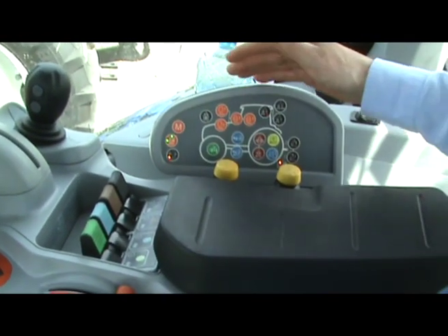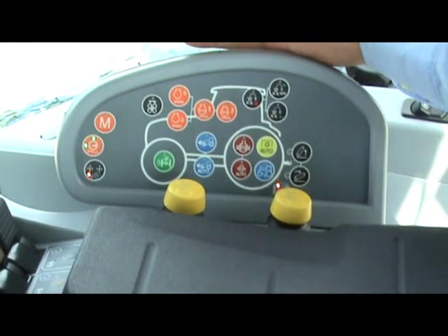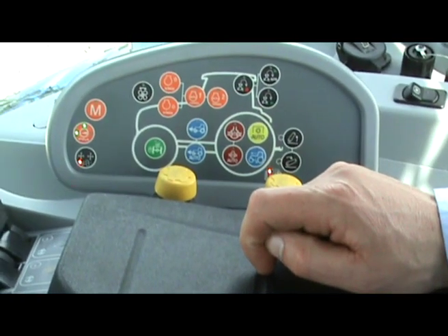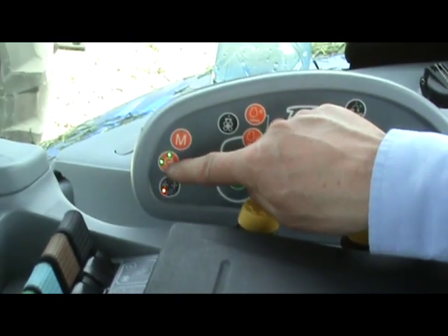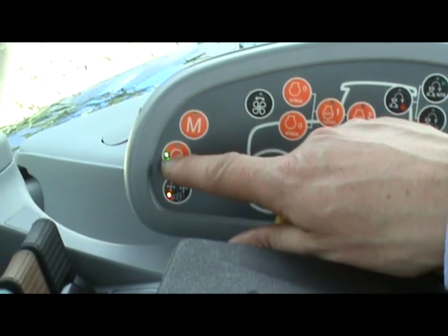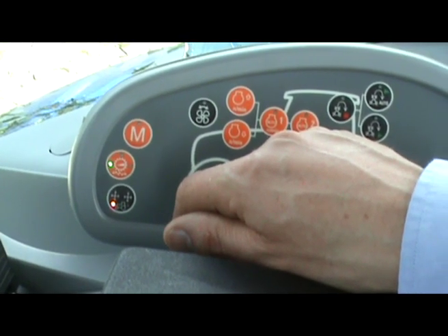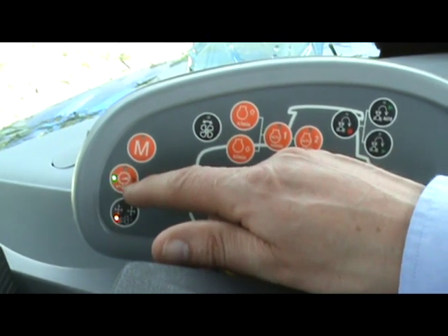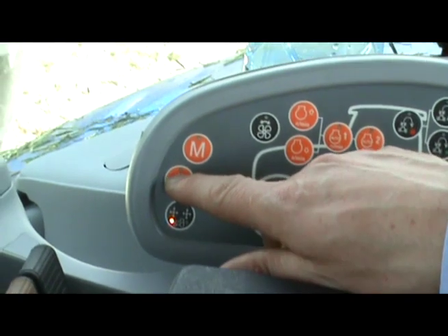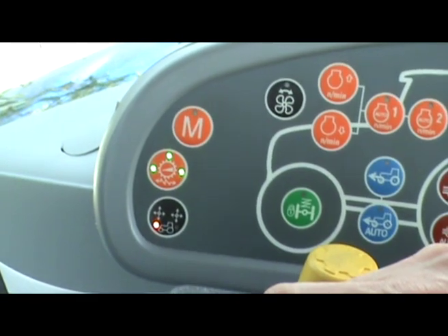On the side of the Sidewinder we have this so-called integrated control panel, and on here are the secondary functions, things that you're not adjusting or controlling all the time, so engaging forward drive and diff lock controls. Got a sensitivity aggression mode for the auto command CVT, which is simply selected on 3 LEDs. So this affects how fast the tractor changes speed. Also it affects the shuttling aggression, how fast it changes direction. So if you wanted a nice leisurely forward to reverse change of direction, you'd have 1 LED lit. Again, if it was working on a buck rake and you wanted a more rapid forward and reverse change in direction, you could have 3 LEDs.